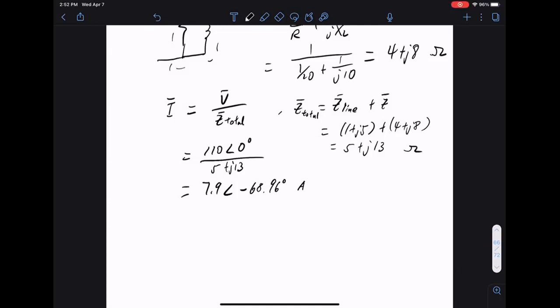No, you do not divide by √2 again. They're already RMS. Yes. Thank you, sir. For that question, you can either just multiply by the current conjugate, or you can do VS cosine theta over sine theta. That's the same thing. It will work out to be the same solution. So it's rather similar to this question. This example is a little bit more complicated, right? So I find the current.